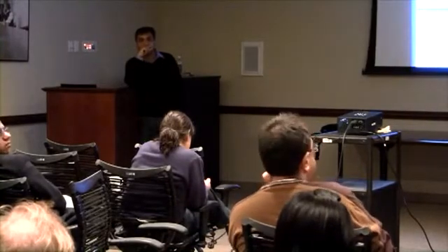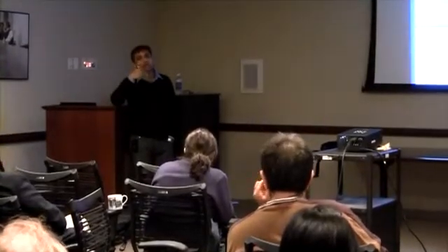Well, nowadays the designers will never let silicon real estate go to sensors. So how do you optimize the number of sensors that you need? Yes, we wrote a paper last year, 2009, on how many sensors you need and how you should smartly place them. I'll talk about that. You're right that if you go to Intel and tell them, why don't you put one more sensor, they'll say get out of my office. That's their attitude.